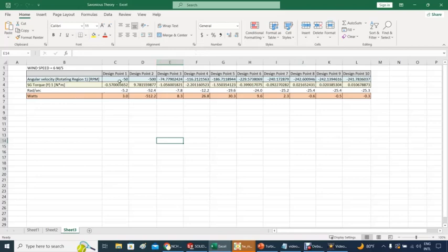Now, if you change the angular velocity to rad per second, you get that. Now you multiply this rad per second by the torque, which is Newton meter, you get watts, and here's the watt. So obviously you can't turn the turbine at 500, because then you will be adding about 512 watts to the system to get that done.